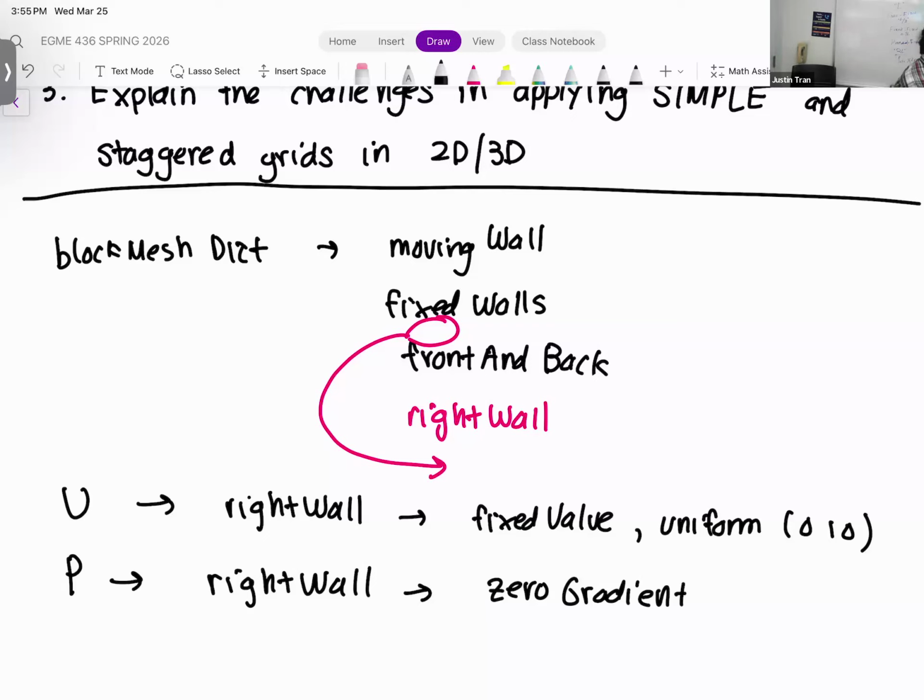It gave another error. It said it was missing the variable under the nut one. Ah, okay. Yeah, that one I don't know what to do for that. I went as far as to throw it into every single one of the subdirectories from 0, and it's still giving me an error. Oh, really? Mine went from the blockMeshDict, we fixed that, and after that, it gave me a controlDict error. They kept giving him an error message of polyMesh not calling a variable correctly.